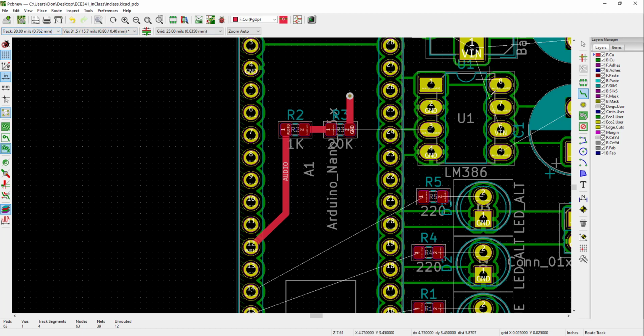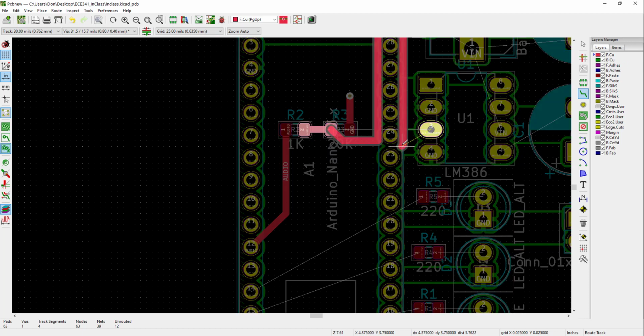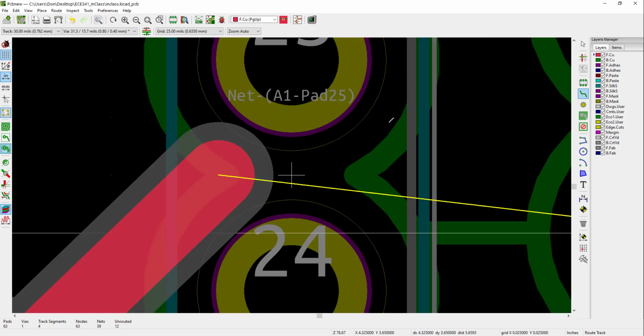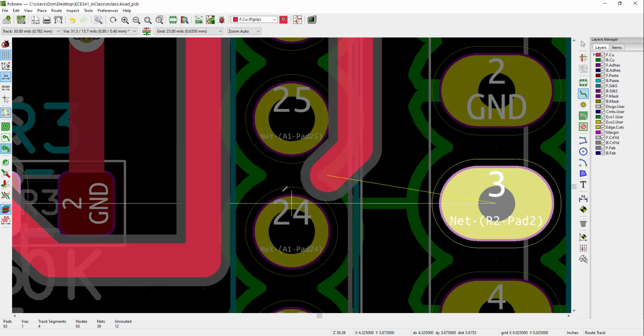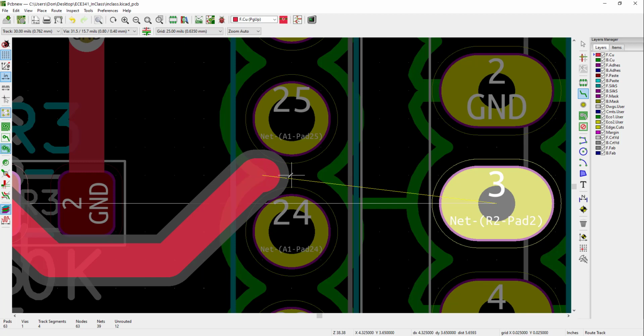So now, if I want to go ahead and connect this center point to this pin, I'll again continue to draw. I'll pick it out. Uh-oh, it looks like I can't fit through this gap. And that's because of my thickness of line combined with my offset. If we zoom in really close, you see this yellow circle, both on the top and the bottom? Basically, that's my keep out. And looking at my red line, it can't fit through this little gap.